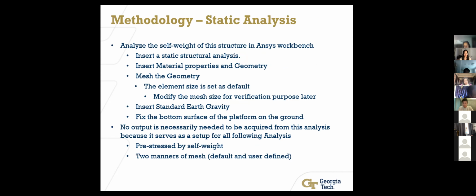And then we insert the standard Earth gravity and fix the bottom surface of the platform on the ground. No output is necessarily needed from this analysis because it serves as a setup for all following analyses. From this setup, all the models are pre-stressed by self-weight in later analyses, and two manners of mesh are adopted.